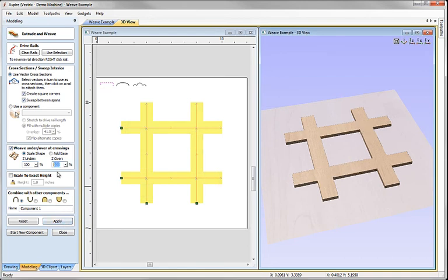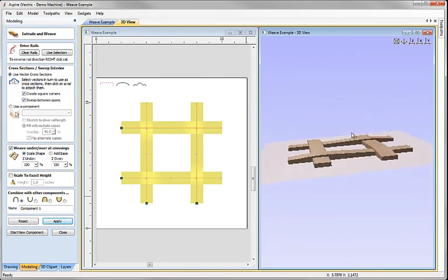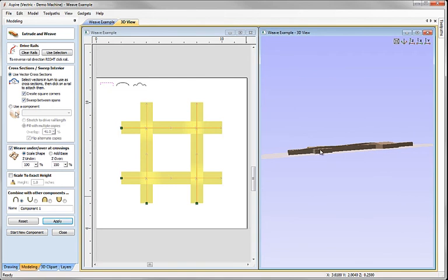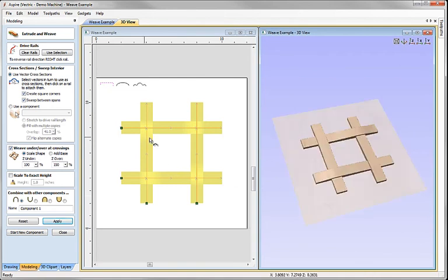And what I could do now is change the Z over, so that is set to 150%, hit apply. And now we can see instead of it going under at these places, it's actually raising up in the other locations, again by 50% of the original height of that particular cross section. And we could do that simultaneously. I could go 50% under and 50% over, and now we've got the effect of it going up and down into those areas where each of those vectors crosses over.